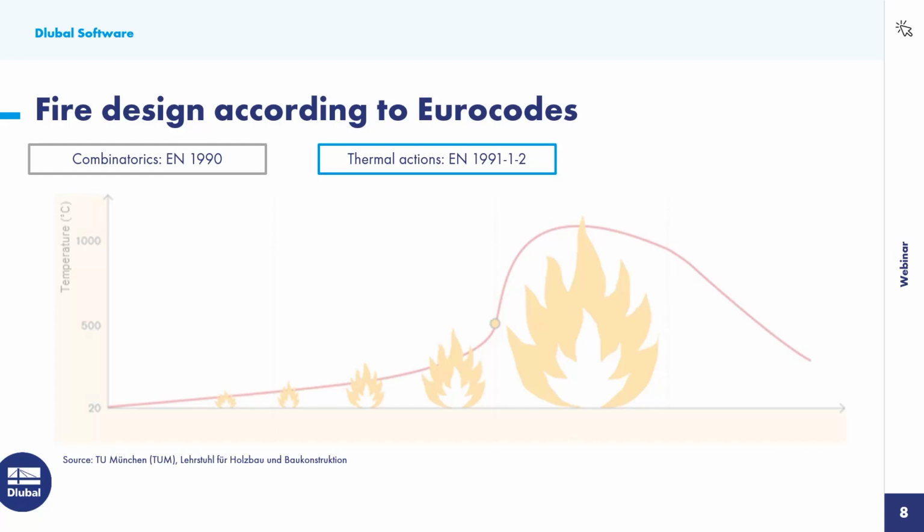Instead of trying, so-called nominal fire curves have been established almost 100 years ago to describe the temperature developed in a compartment over the duration of the fire in a simplified manner. The standard temperature curve is used for fires inside buildings. This temperature curve is also used for standardized fire tests on structural elements, which means that the behavior of typical elements under this nominal fire exposure is quite well documented and verified.